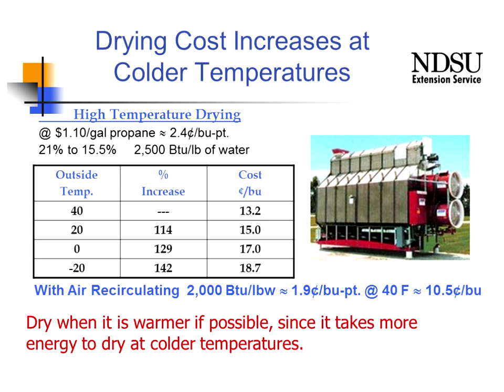And frequently what we find is that we're better to start harvesting that corn as long as we're in the low 20% moisture range, do some of this drying when outside temperatures are much warmer, and then eliminate drying when it's very cold.